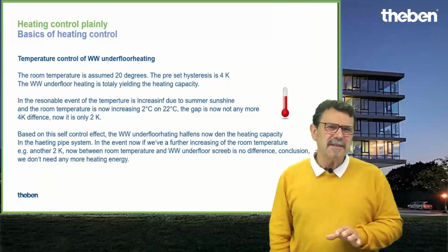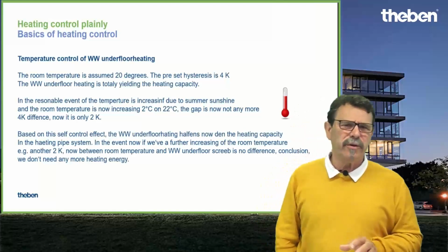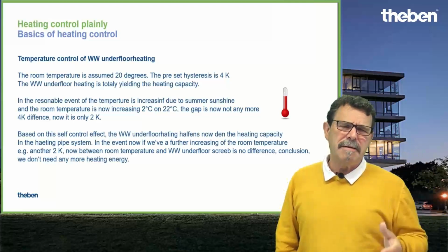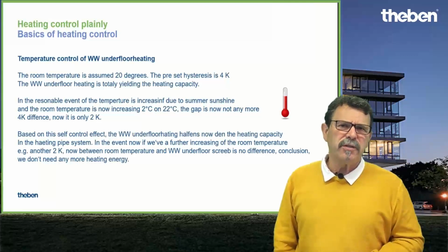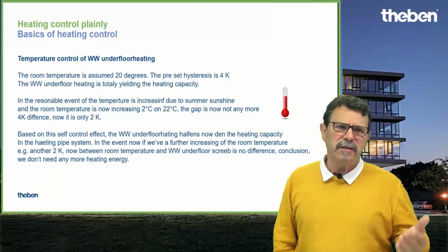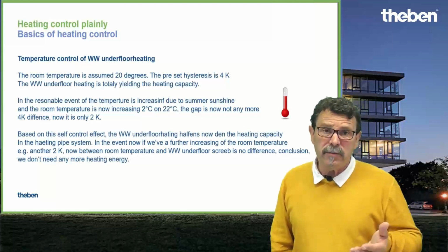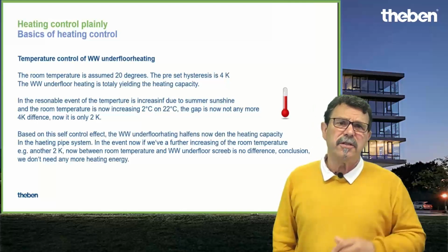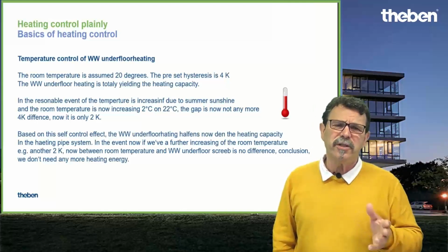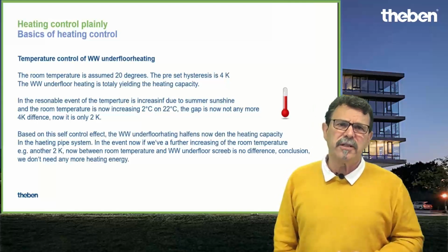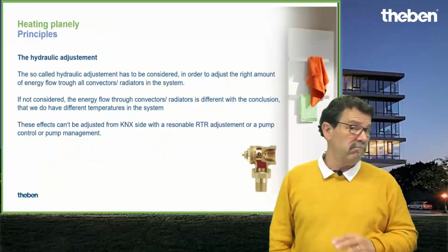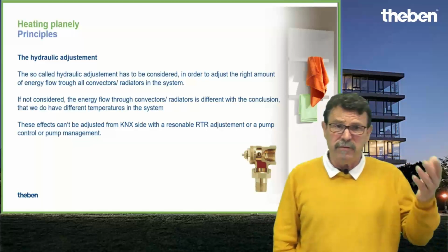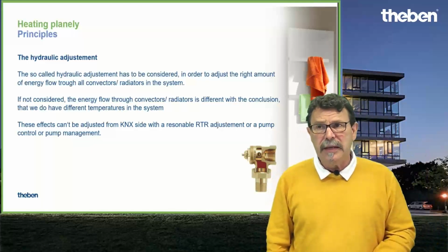Otherwise, it is not that efficient anymore, because it depends always on the screed and the insulation which we have. And when we reduce the temperature too much, you need next morning a long time to heat up this system again. And so the energy efficiency is not that good. So 1 or 2 degrees maximum night reduction, that's it. A recommendation with experience of more than 25 years.